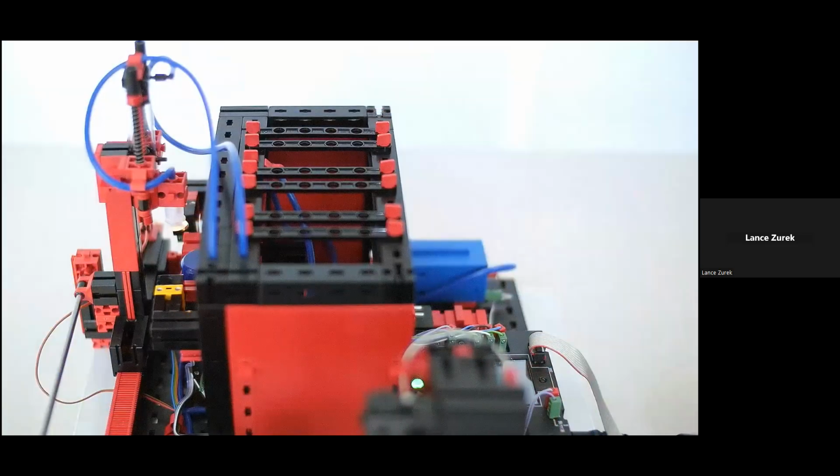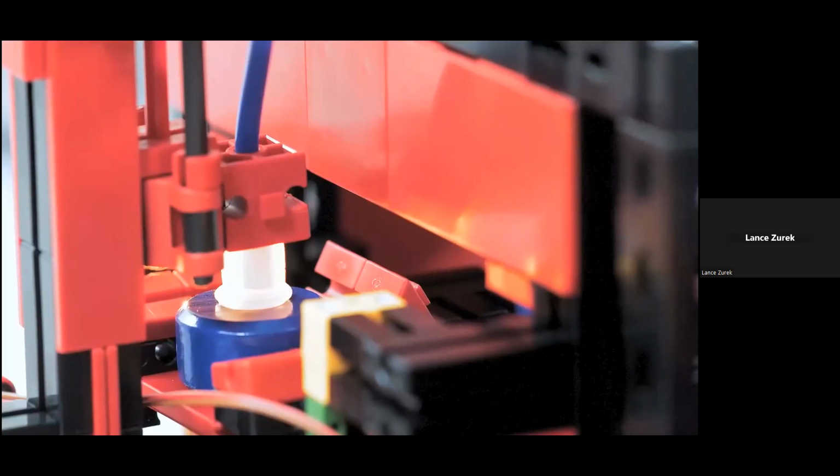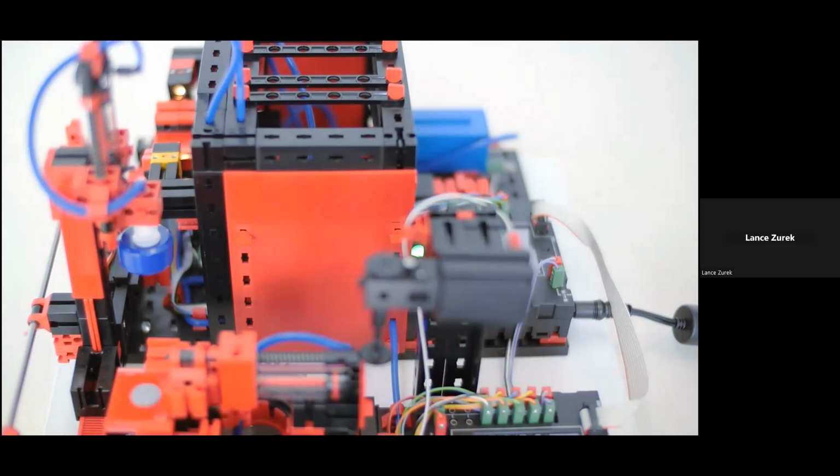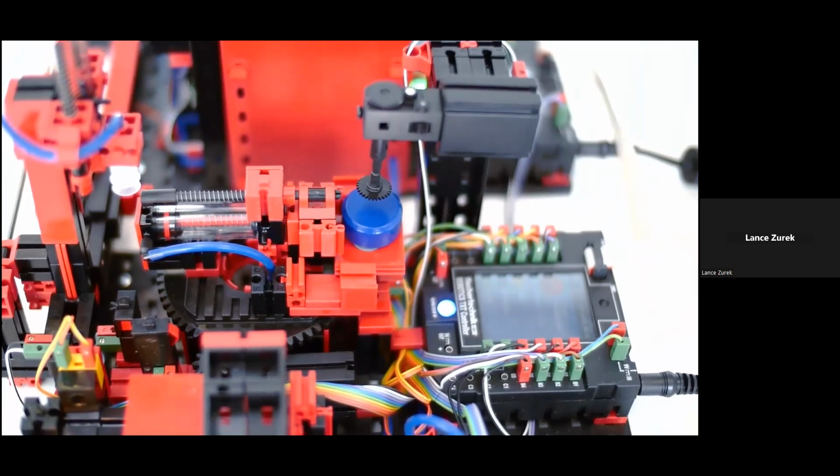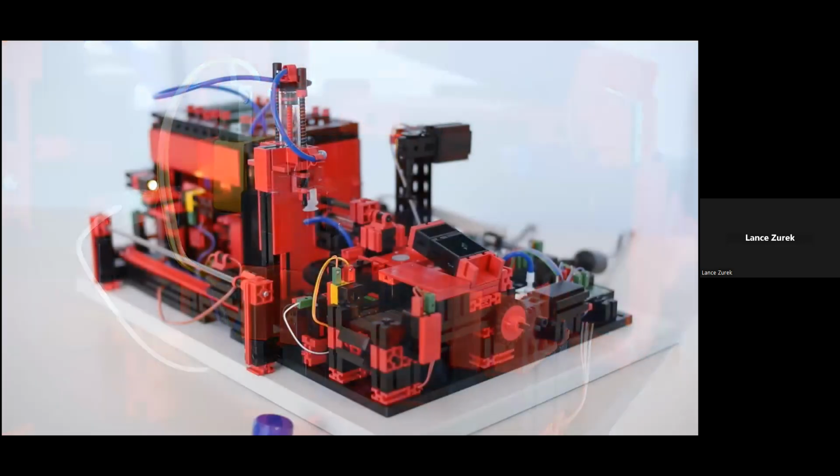Again, the standard version of this model is the 24-volt version, for use with the PLC of your choice with the relay board for motor polarity reversal and both a multi-pin connector, again 34 pins with a grid of 2.54 millimeters, as well as additional PCB terminals with push-in connections for all inputs and outputs. And the limited edition 9-volt version in this case is connected to 2 robotics TXT controllers. So in this instance, 2 120-volt power adapters will be required for all operations.